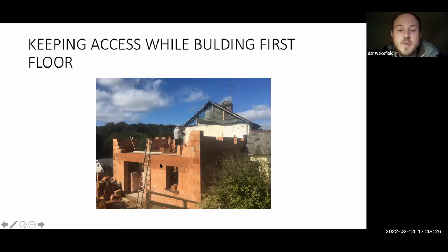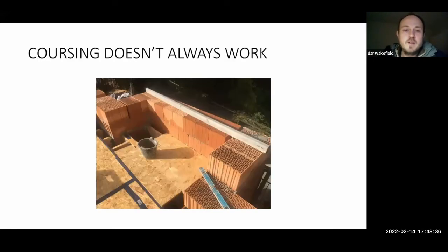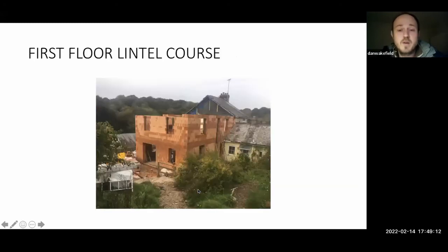It's all about managing the materials. You've got this huge volume of material that you're trying to move around all the time. And coursing doesn't always work exactly. Ideally you'd dimension everything to the dimensions of the block, but sometimes it's not possible, and you can end up with awkward sizes where we end up cutting really thin slithers. Even if you had designed it to be the right size, sometimes it just didn't quite work, and we ended up having to put infill slithers in various places, which was annoying.